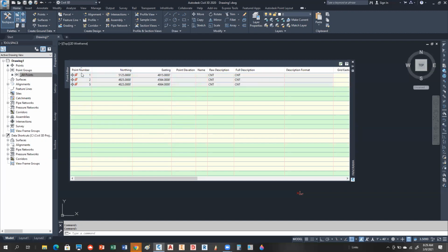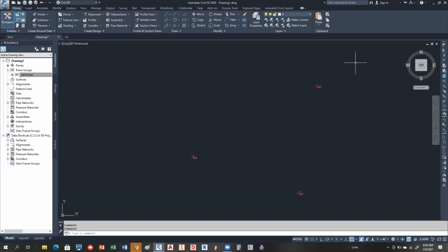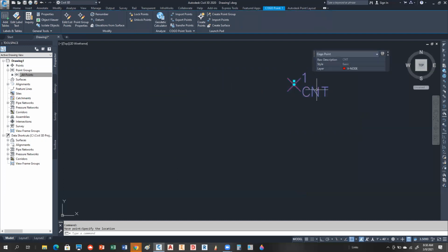So you should see this lock symbol that occurred here. What this means is these points can never move now. All right, they're going to stay intact. Once you get your coordinates correct, and once you've locked them, you can dismiss the panorama. So if I try to come here now and click on that grip, it's not going to let me do anything.